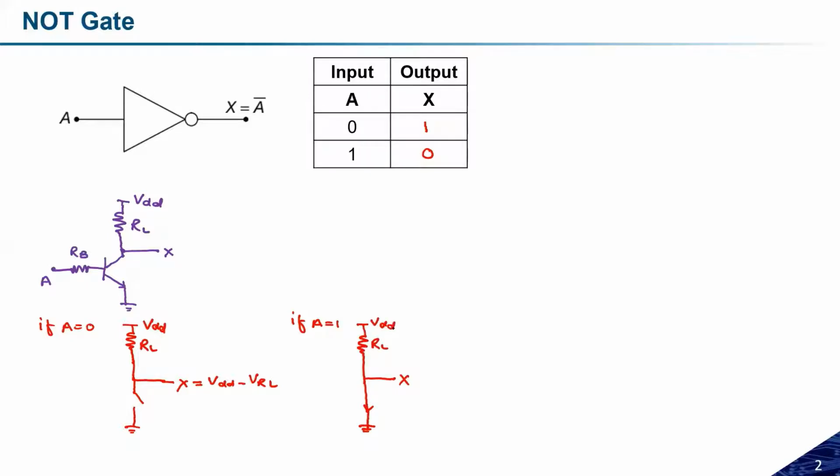Now, because this is short circuited, the resistance between X and the ground is less than the resistance between VDD and X. So the lower part will start dominating, because the current flow between X and the ground will be more as compared to VDD and X. Because there is less resistance, X will be grounded, but definitely this RL will try to pull up.